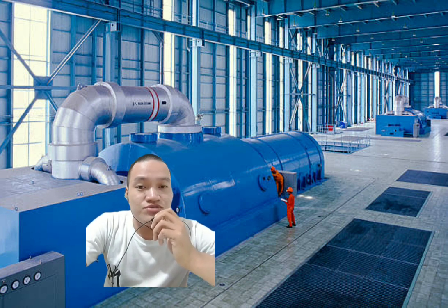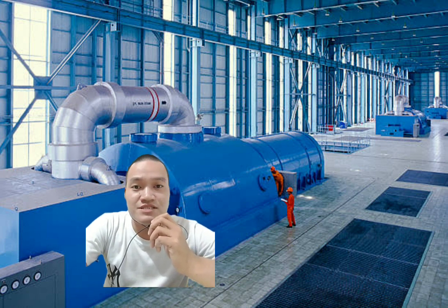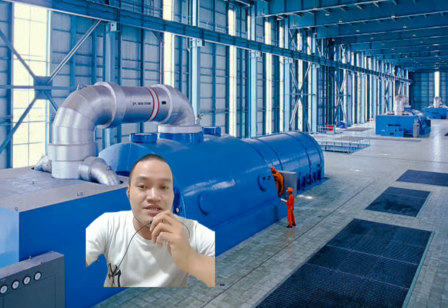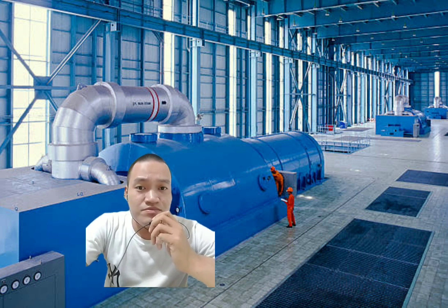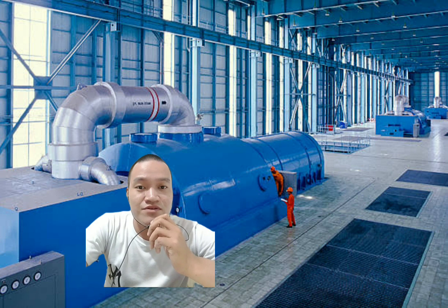Then the gland sealing should now be partially opened and the vacuum increased. The turning gear can now be disengaged. Then, through the main valve, short blasts of steam are now admitted to the turbine to spin the propeller one revolution. This should be repeated every 3 to 5 minutes for a period of 15 to 30 minutes. The vacuum can now be raised to operational value, and also the gland steam pressure. The turbine is now ready to use.